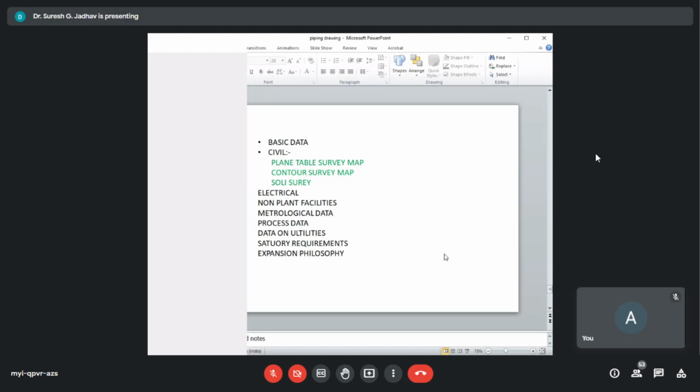In the plane table survey map, this document shows the extent of the plot with overall areas, identifying all the existing constraints such as transmission lines, structures, fences, places of worship, if any, etc. The survey covers 20 to 30 meters beyond the extent of the specified plot to show the nearby roads, drains, and broad features of the neighboring plots.